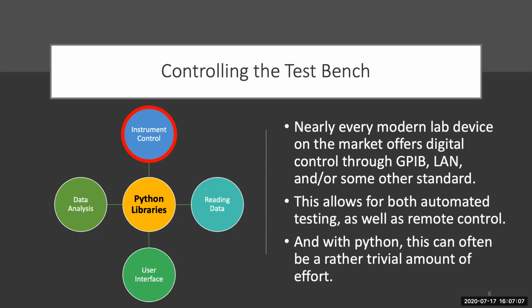So this ADC or whatever chip you're trying to test operates on a large voltage range, or it's supposed to work on some voltage range, and you want to gauge its performance across this entire range. You could sit in a lab and manually tune your signal generator and save its result, or you can just program your signal generator to scan through an array of voltages. Okay? So let's work through a demonstration of this.